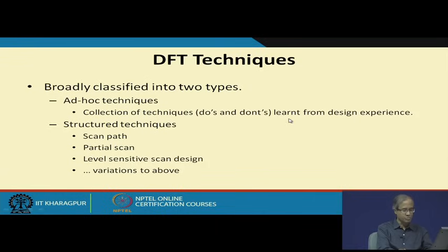If you follow those rules, then your circuit will be a little better from the testing point of view. But structured techniques can totally solve the problem, as I have just mentioned. Here we shall be looking at the scan path approach. There are variations to the scan path approach, partial scan, level sensitive scan designs, and several others. But if you look at the basic idea behind scan path, you will get the feeling of exactly what we are trying to do.